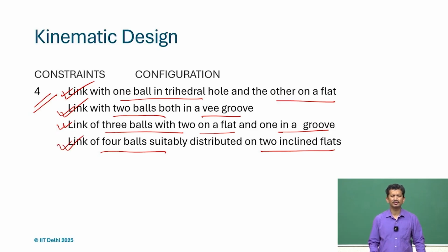Good thing is, if we try to animate using this kind of assembly mating, what we realize is that if it is exact constraint design and we change any of the parameters, so any deviations you have in the parts, it just shifts and moves to different locations, but the assembly is still valid.